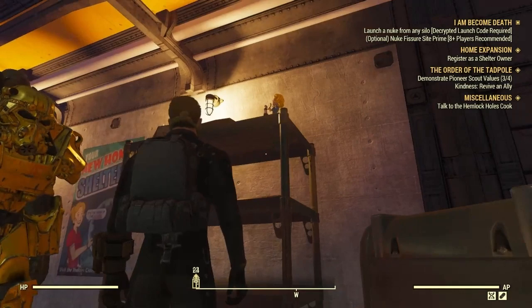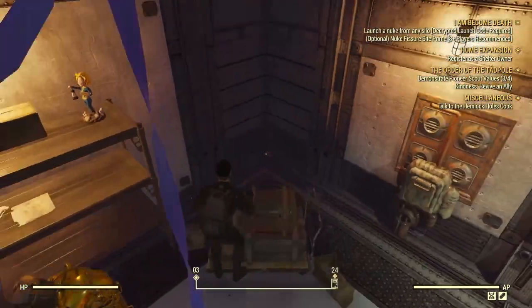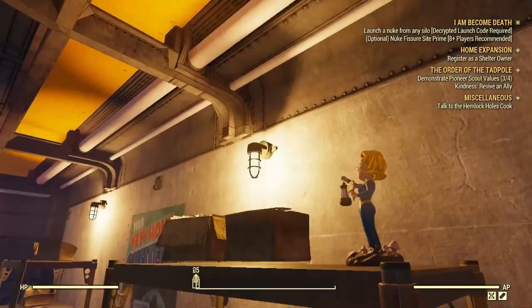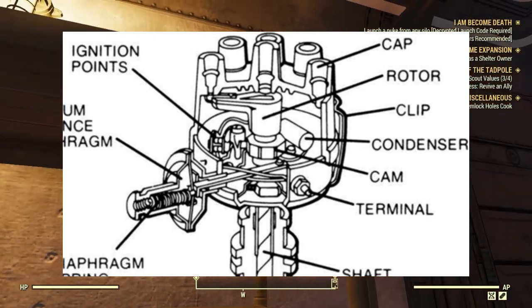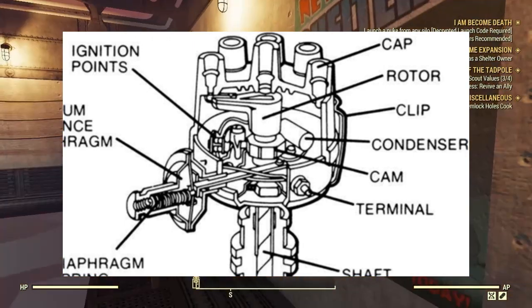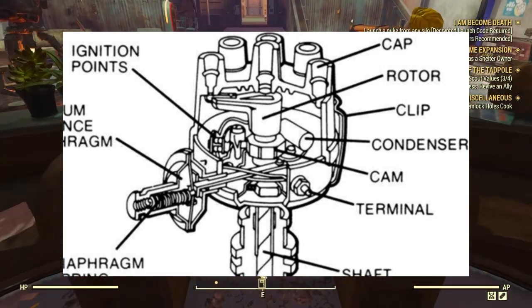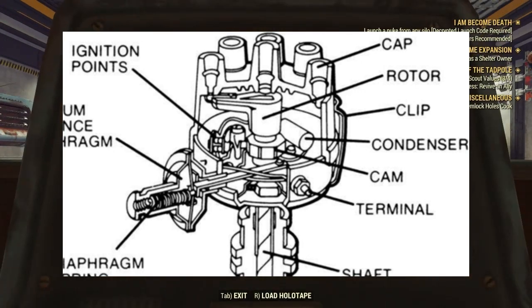That would go to a shaft going up into the distributor, which back in the old days had a couple of electric components in there, and a small little tab that would open and close 2 little touching points that ironically are called points.